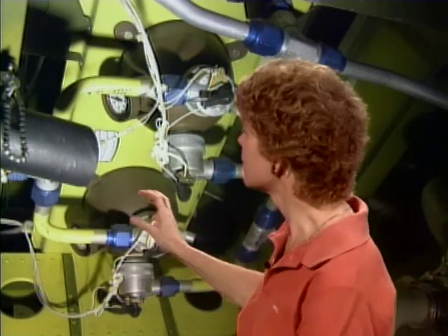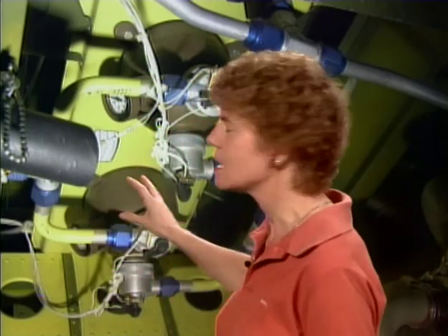Now, you can check the containers to determine their charge, and one way to do that is by weighing the container and its contents. By weighing it, you can tell how much of a charge it's got in it. The fire extinguisher container should be replaced if, when pressure checked, it is found not to be between the minimum and maximum limits. There are minimum and maximum pressure limits depending on temperature, and if it's not within those limits, it needs to be replaced.